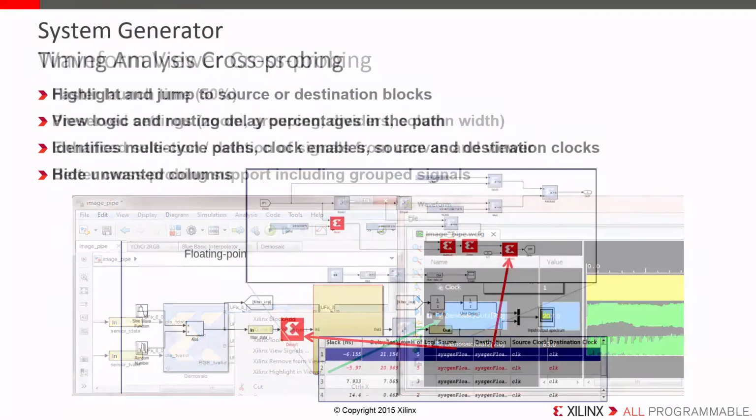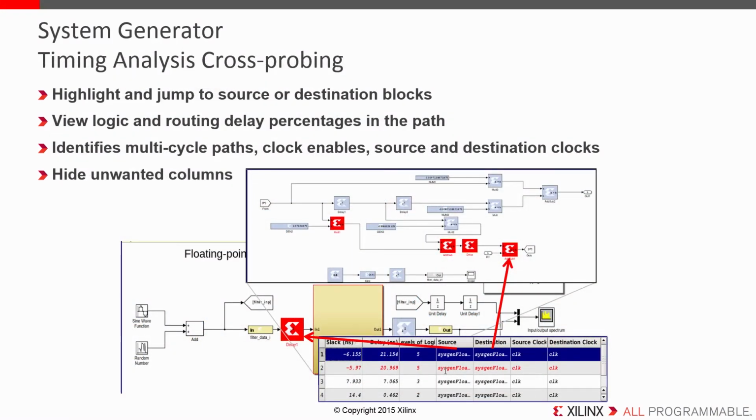We've also improved the timing analyzer integration within System Generator. Timing analysis is available for all netlisting flows, including IP catalog generation. After packaging the IP, the design can be optionally timed after either synthesis or a fully routed implementation. The synthesis is faster, but the implementation option is more accurate, and both versions are automated for the user. The resulting analysis table lists the failing paths first, but you can also show your passing paths too, and these would be highlighted in green.